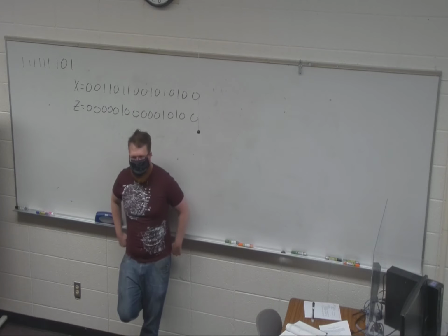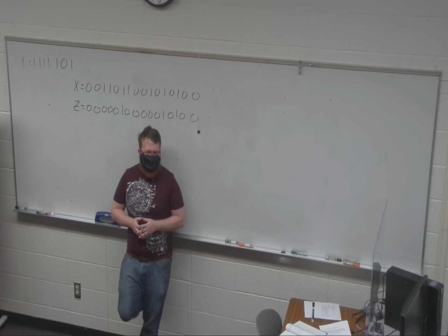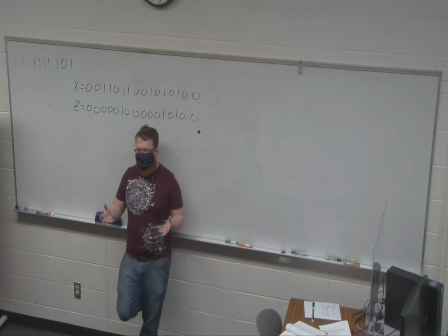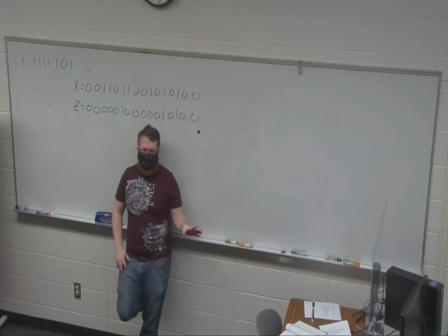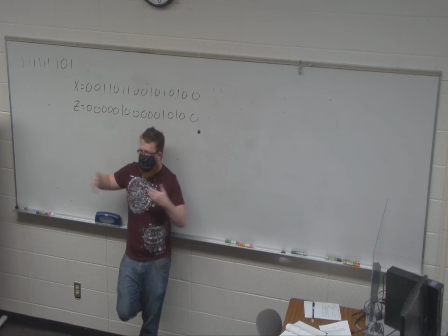Very large, right? We're not very creative with naming oftentimes in this industry, but part of the reason we use that very large is because if you have a signal generated on one side of the chip and you're sending it all the way to the other, there can be enough delay, and we call that propagation delay. This term, the book uses it exclusively as a term in the devices. So if it goes through an inverter, it gets delayed, and that's propagation delay. But it can also go through a wire that's really long, and that can be propagation delay.